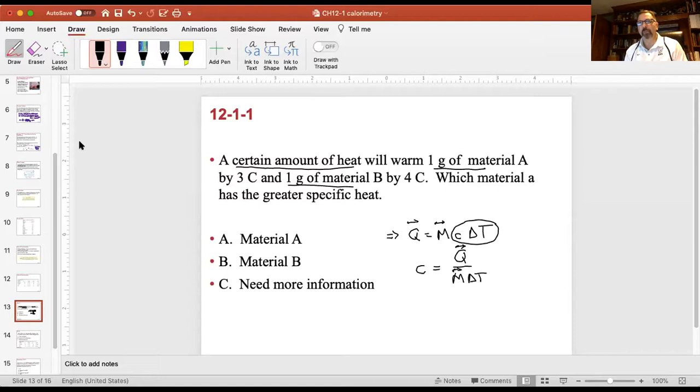So C there has that. It's almost like temperature inertia. The bigger C is, the harder it is to change the temperature. Just like the bigger the mass is, the harder it is to accelerate something. And I think that's a legitimate way of viewing it. Although the analogy is rough, the fact is mass and acceleration are multiplied together, just like specific heat and temperature are multiplied together. And so they must be inversely related. All right. Any questions on that?